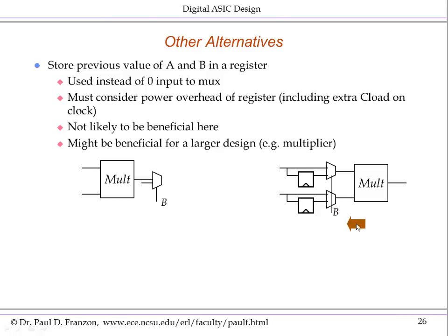And this is assuming I don't want whatever comes in here to be multiplied. And this could save quite a bit of power at the expense of these additional registers. So this is particularly useful if B changes a lot. If B was a low activity factor, the switching to the zeros might be lower. How to decide these things? Well, again, a table like I have on the first page could lead to detailed guidance on how to choose these alternatives. You'll see some exercises around scenarios like this in the quizzes associated with this section.